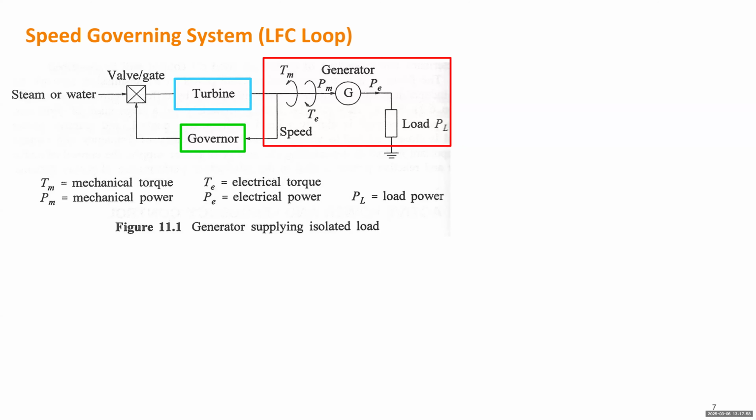All right, next we can talk about how to model the turbine governor. In the previous session, all the modeling work has been done for the right box. We model the generator starting from the equivalent circuit, and we introduce power transformation to have a D-axis and Q-axis circuit, and gradually derive the differential equations and simplify the model. The simplest model just uses the swing equation to model how the mechanical torque changing from the electric torque can cause a change on the speed and angle. That's what the swing equation is talking about.